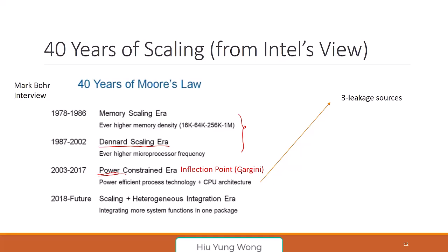And this is what the paper I put in the canvas talks about. Nowadays, we cannot just improve the transistor. We need to make efficient technologies, okay? And then how are we going to solve it? A lot of content is about this, right? And then in the future, it's about scaling and heterogeneous integration, right? As I said, while you cannot put more transistors in a die, can you stack more dies in the same package? Then isn't that also another kind of Moore's law?